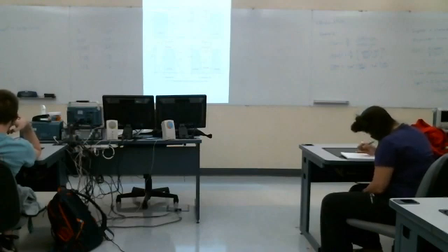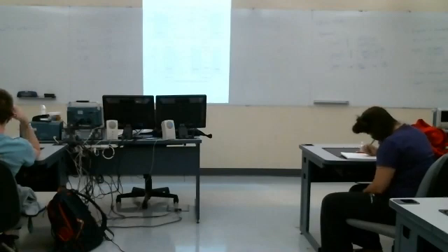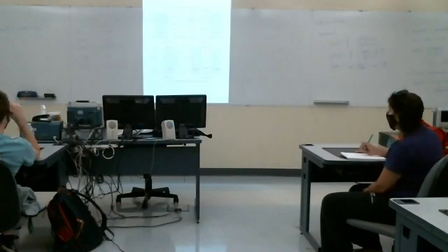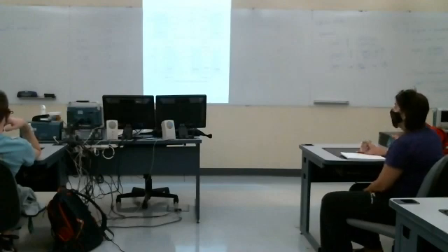So to draw these terms, it's just these two pieces. A line at a dB value of 0 to the left of omega c, and then another straight line that goes up at a 20 dB per decade rate to the right of omega c. Now this 20 dB per decade rate is also the same as, very approximately, 6 dB per octave.